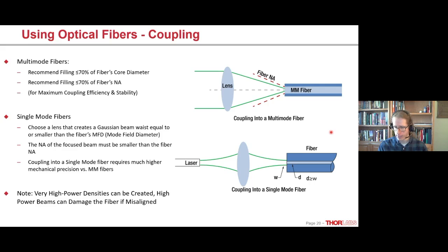Of course, we know the index of the silica glass core, so we know the speed of light in the silica. And so we can actually tell from there how far into the fiber spool we have some sort of reflecting thing. And the main thing that's going to reflect is if the fiber is broken, now you get Fresnel reflections at that broken piece of the fiber, at that end face, that probably not very nice end face. And so that way, we can actually fault check a fiber and look down kilometers and kilometers and kilometers of fiber and detect those breaks in fiber that we can't see with really, really good spatial resolution.